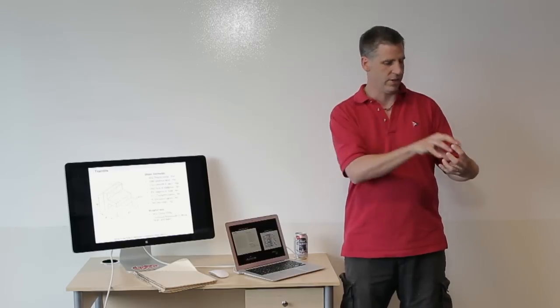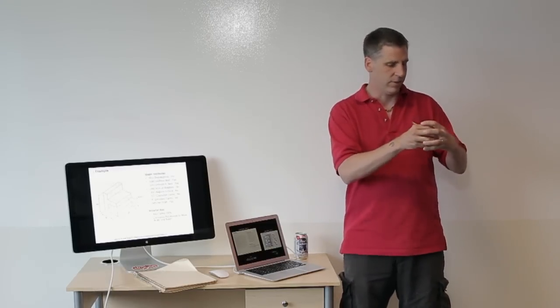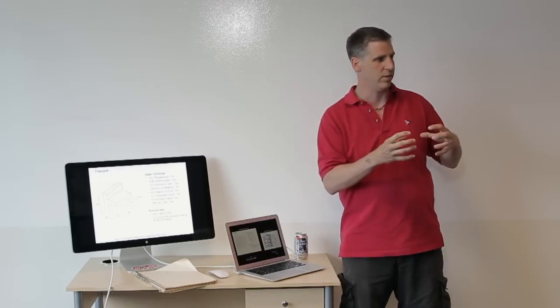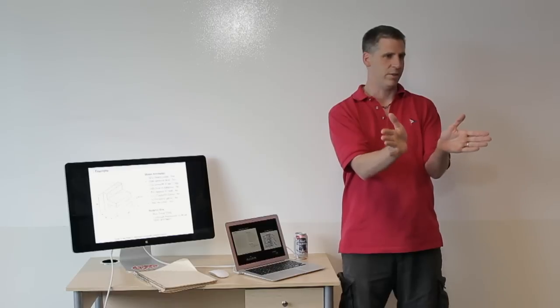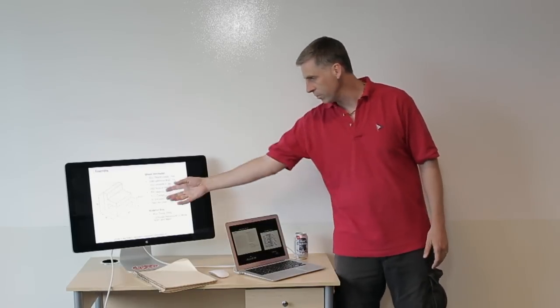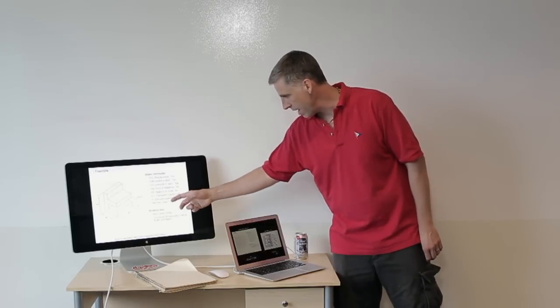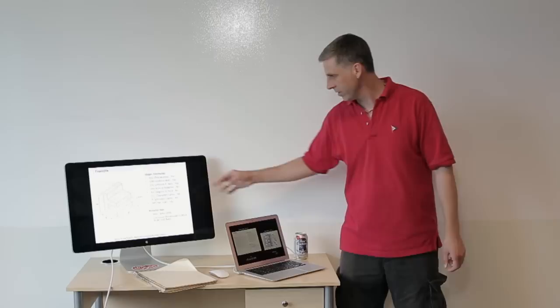Usually what we'll do is have ejector pins, which if you look on the back of any plastic part, you'll see the witness lines or the little circles where it was pushed out. But regardless, no matter how many ejector pins there are, if it's a straight wall, you're going to scratch it and it's going to squeeze very tight. So what we do is we put draft on it, which is a little bit of an angle, usually about 1/2 degrees. So think of the cup in your hand. You can imagine how that has a little draft, and it will pop off nice and easy. So with this part, it's straight wall, there's no draft. All injection molded parts, though, if you look at them, will always have draft in them. So no draft, correct.